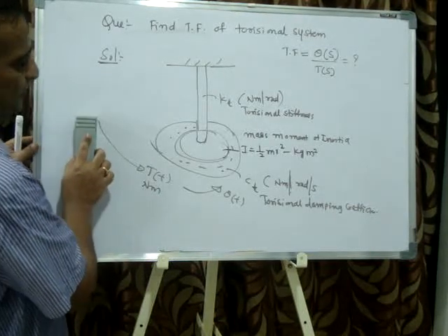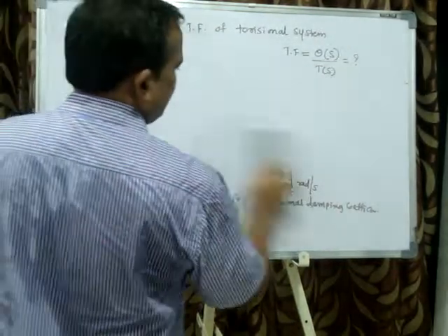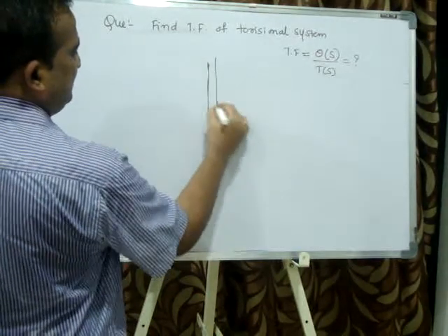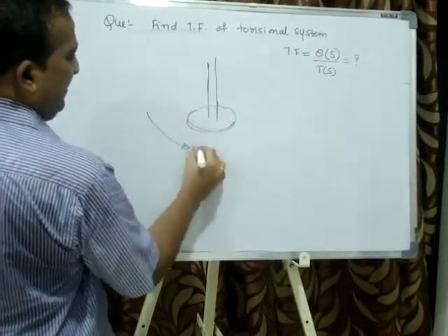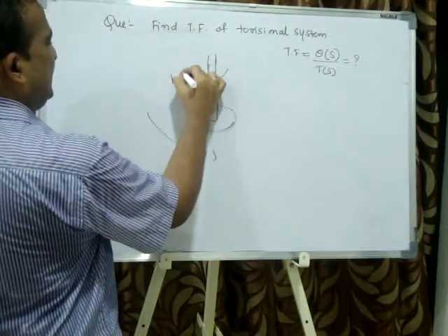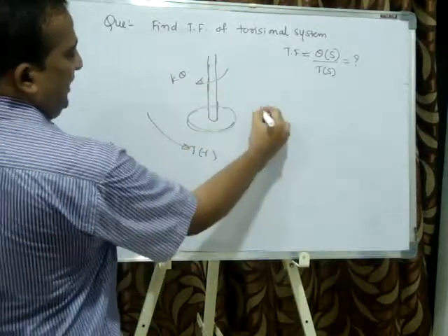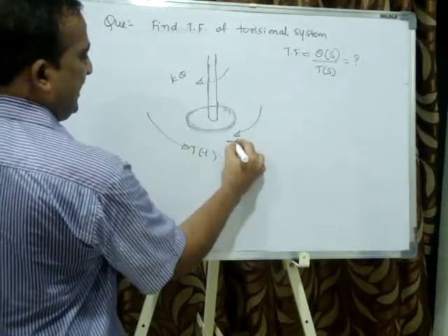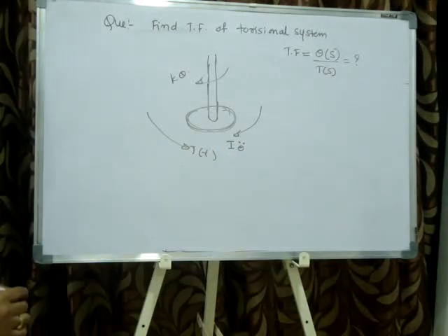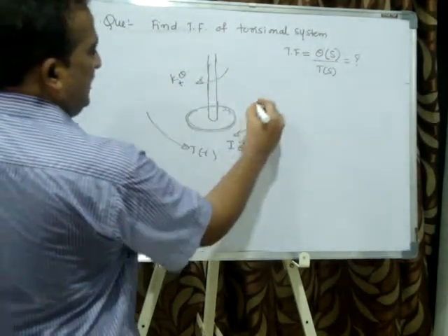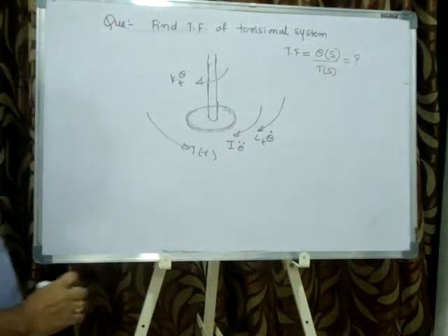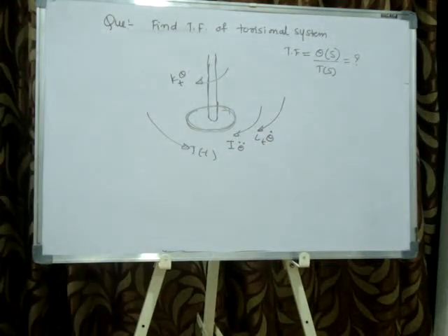Now the free body diagram I will take like this. When you try to apply the T of t, immediately the steel rod, the torsional spring, opposes with k theta, and due to the disk mass, I theta double dot. This is called inertia torque and stiffness torque, and one more is the oil, that is called damping torque. All three are opposing the external applied torque.